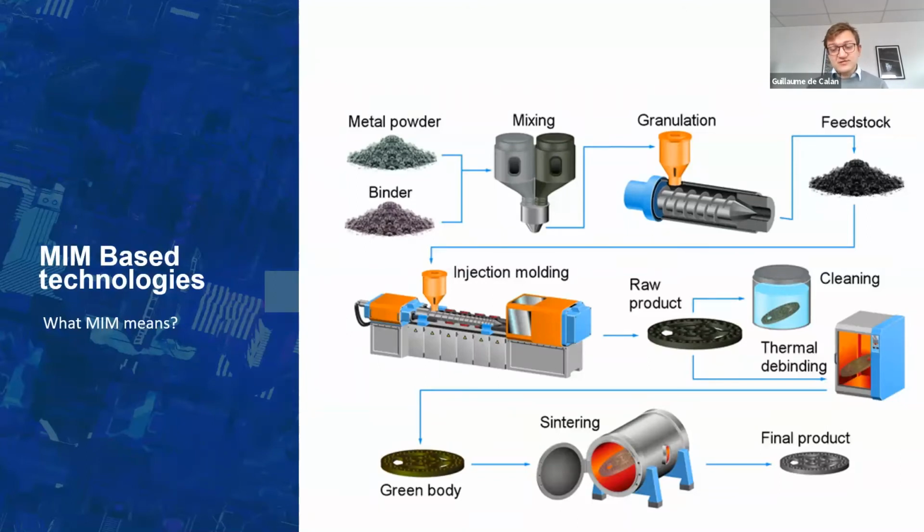And again, a small thing, what is sintering? Sintering is a densification of the part in the solid state. That means we don't melt the metal, we just heat it up enough that the part will densify. And you can see on the pictures that this densification means you're going to have a shrinkage, of course.